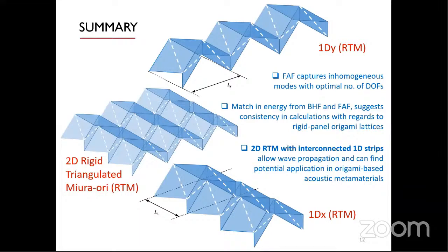Verification of the folding angle formulation proposed here with the existing bar and hinge formulation confirms the authenticity of our findings. Since folding deformations at creases are typically associated with lower energy, our research shows the potential for use of origami lattices in low frequency wave propagation based applications like acoustic metamaterials and waveguides.